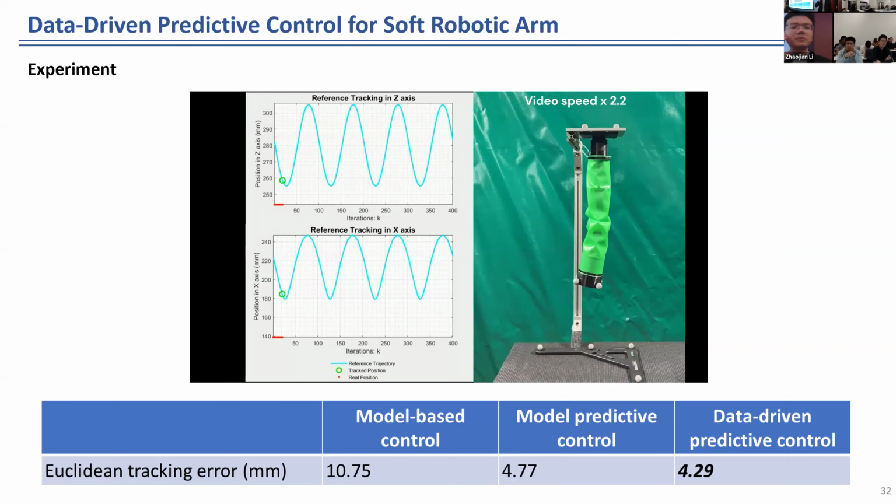And limitation wise, the benefit of the vacuum is that we will have sufficient airflow rate. So even though the localization is a little bit off, for example by 1.5 centimeters, due to the big airflow rate, we'll still be able to attract the fruit. But the challenge from last season was the power consumption. You can see it's a really big, bulky vacuum. We bought this off the shelf. It's an industrial vacuum system, and the power is really heavy. I think it's 1.8 kilowatts. If you think that we're going to have 8 arms, then that's not possible. So that was a big concern.